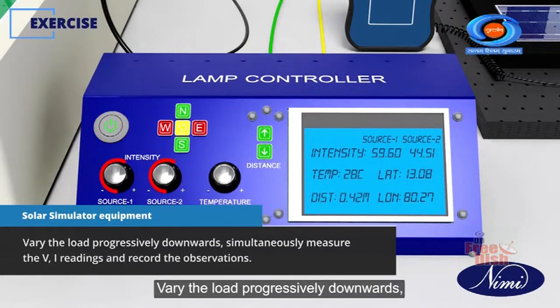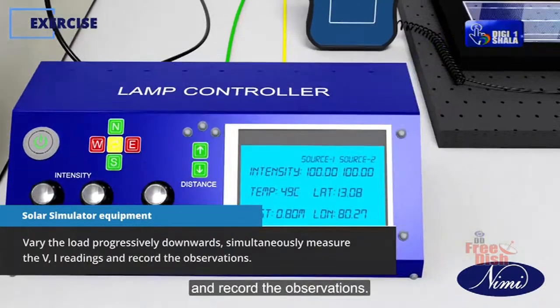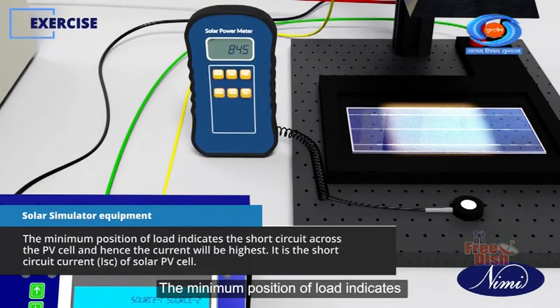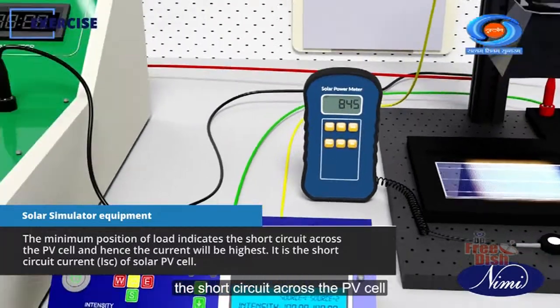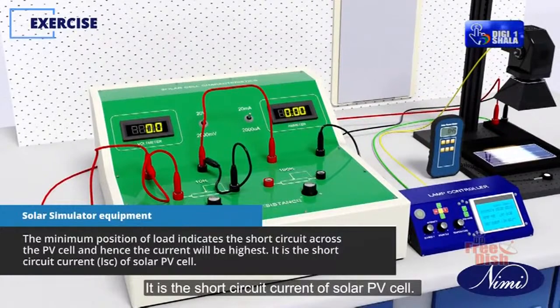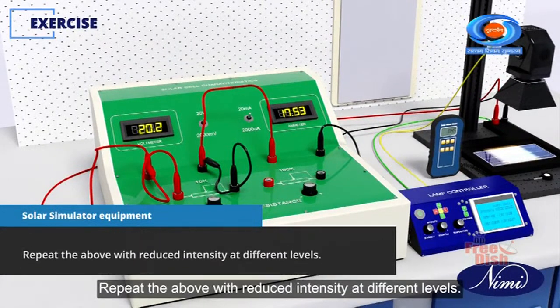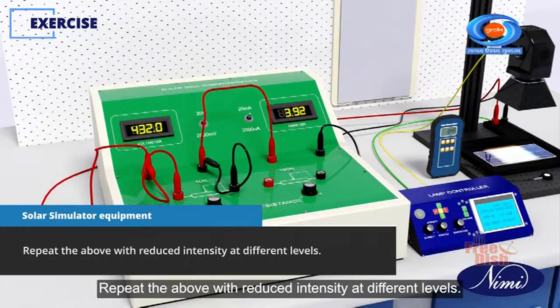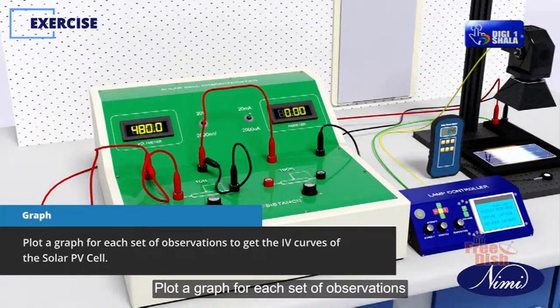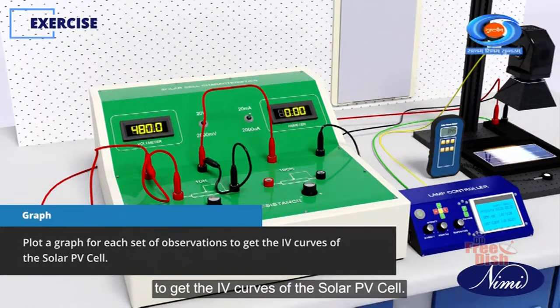Vary the load progressively downwards. Simultaneously measure the VI readings and record the observations. The minimum position of the load indicates the short circuit across the PV cell, and hence the current will be highest. It is the short circuit current of the solar PV cell. Repeat the above with reduced intensity at different levels. Plot a graph for each set of observations to get the IV curves of the solar PV cell.